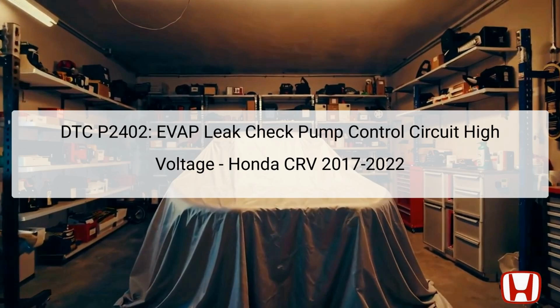The Diagnostic Trouble Code, DTC P2402, pertains to an issue within the evaporative system of the Honda CRV model years 2017 to 2022. Specifically, this code indicates that there is high voltage detected in the EVAP leak check pump control circuit. The evaporative system is critical for capturing fuel vapors and preventing them from being released into the atmosphere. And the leak check pump plays a major role in this process.